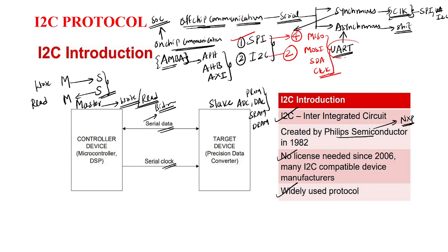And UART is another type of communication. There is no clock in the UART. Here we will send 8 bits of data, with one start bit and one stop bit, which can be either 1 or 0 depending on that. We will make an address frame and send it. At the receiving end, we will compare with the start bit and stop bit and verify that proper data is sent or not. That is one type of communication.